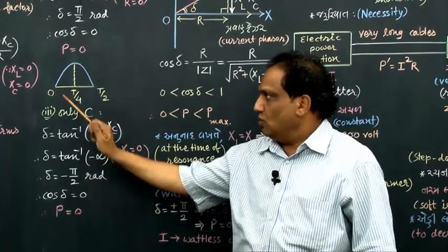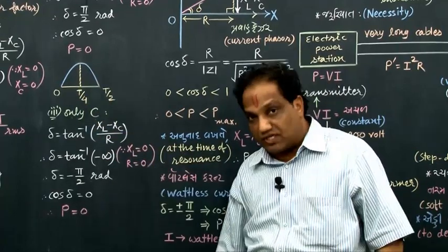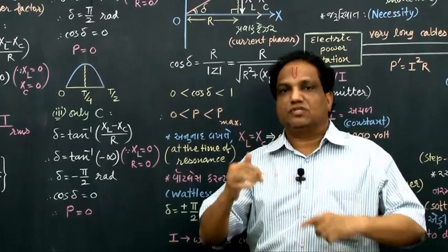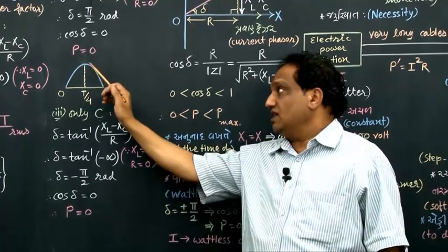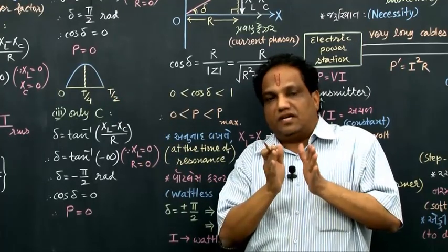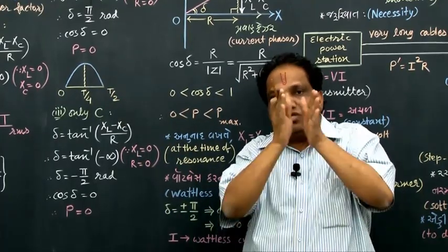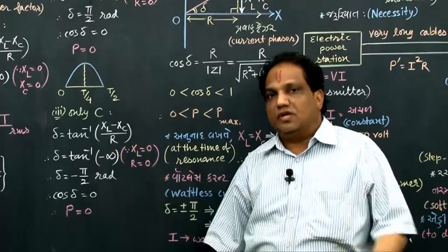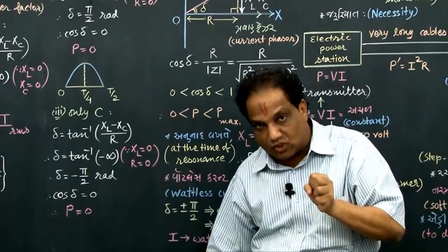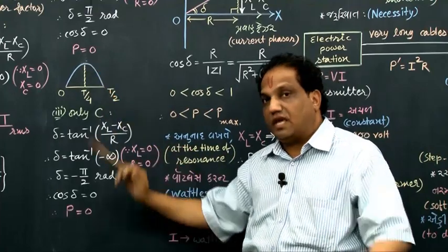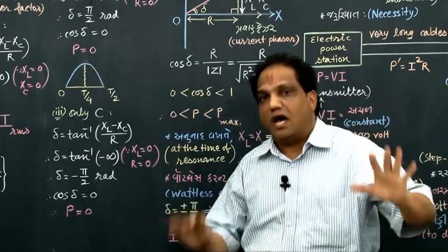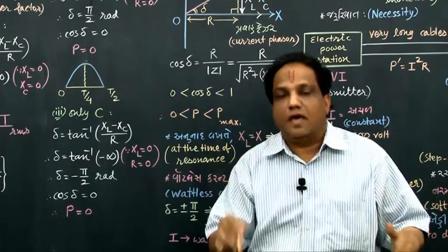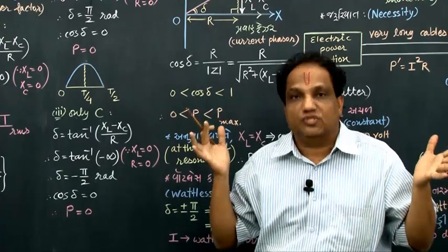I am showing you. During increase of voltage across capacitor, more and more electrostatic potential is getting stored in the electric field because it is the charging condition. During decreasing voltage condition, electric field loses that energy because the capacitor is discharging. I mean to say, during increase of voltage, capacitor gains energy from the source. During decrease in voltage, capacitor loses same amount of energy. So effective or net amount of energy spent in the circuit is 0, and that is why the power is also 0.